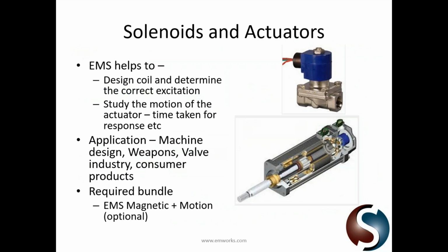Now let us look at some of the application spaces with regards to EMS for SolidWorks, which is really a low frequency electromechanical field simulation solver. One of the first application areas is the solenoids and actuators. In this particular application, the EMS product really helps in understanding how your coil, in the case of electromagnets, performs. What is the excitation of the coil? What kind of flux does it produce? Does it actually produce enough force to move your actuator, and so on? And one can actually couple with a motion simulation to really understand the dynamic response of the movable plunger or the moving component in an actuator or a solenoid study.